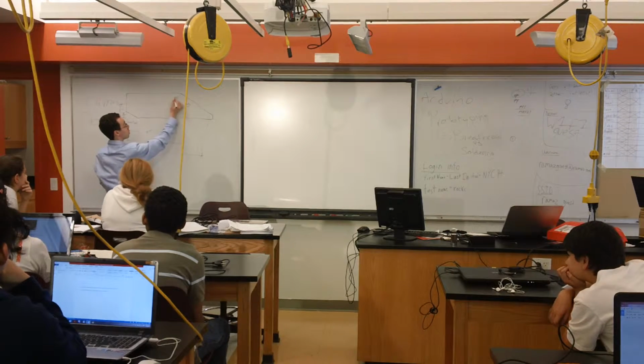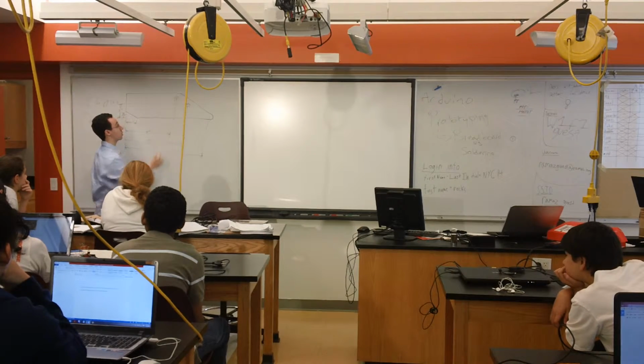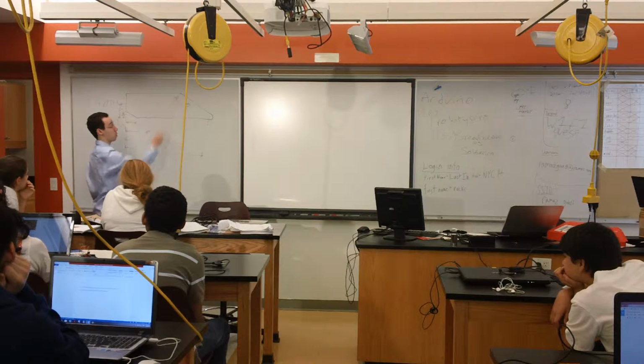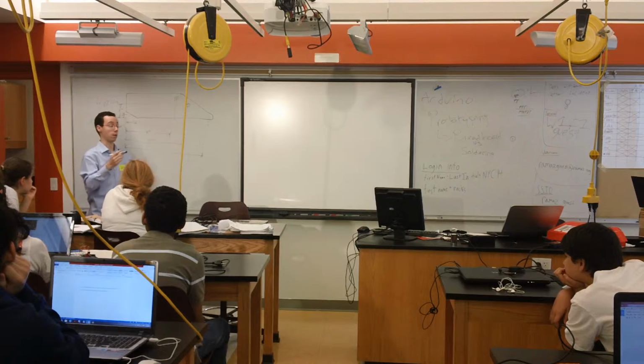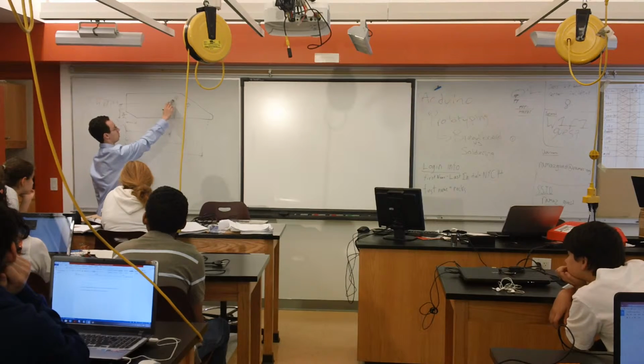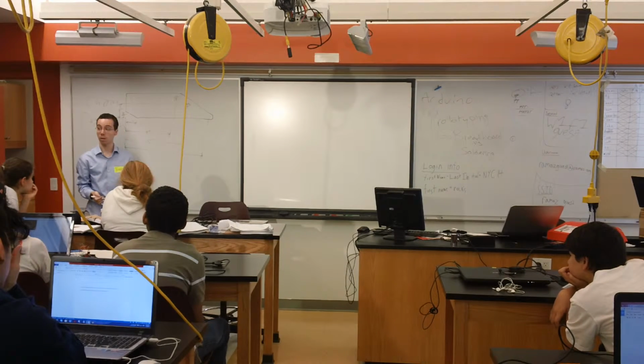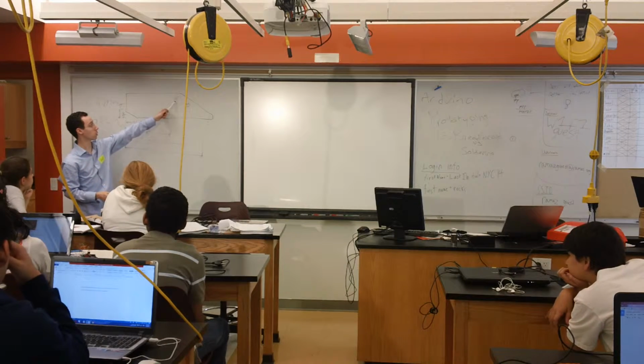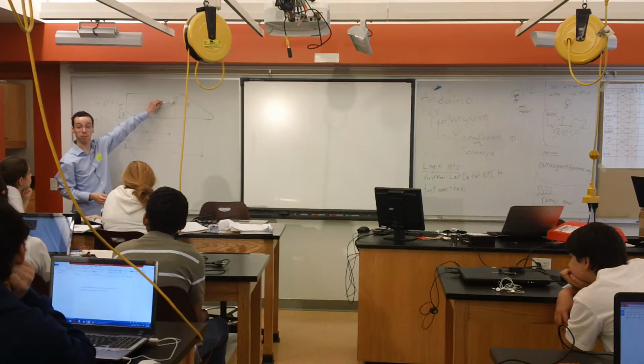If instead I had dimensions to the edge here, then what your machinist will have to do, if I tell you the diameter of this hole, he says, okay, this hole is 1 inch in diameter, so it's a 1/2 inch radius, so I'm actually going to have to go out this distance plus half the diameter. It's a lot more confusing for him. So with circles, we always specify to the center.